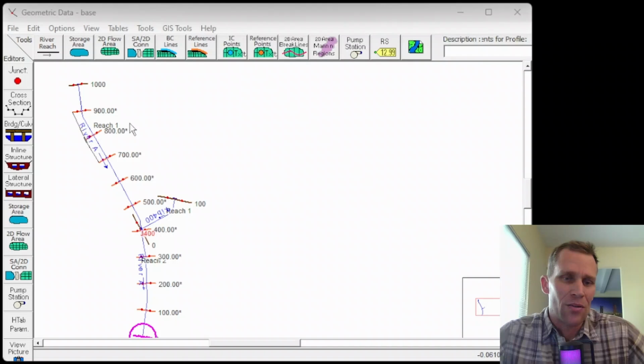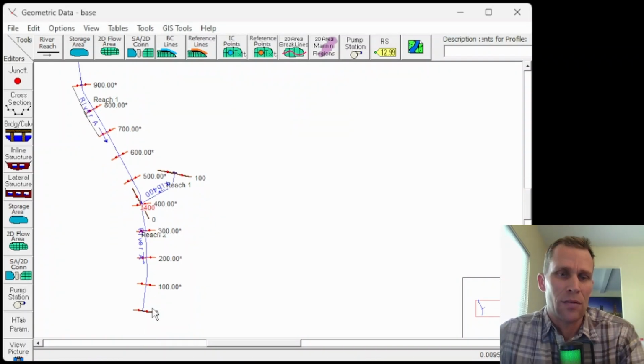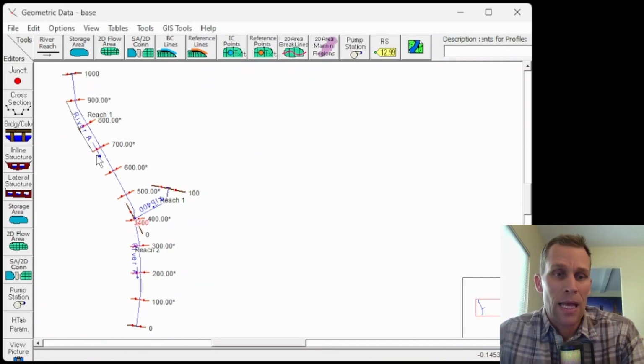What we did was we created a single river reach in 1D flow with an adjoining tributary, and we looked at the freeboard at this downstream location when our river reach happened to have a lateral structure with water leaving, a tributary with water entering, and then, of course, our decision variable, which was the amount of water we wanted to release from the upstream reservoir that enters the reach.